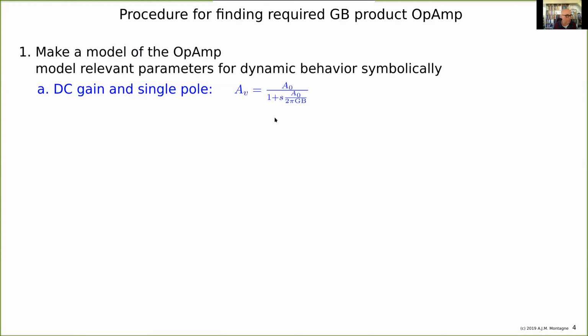Unfortunately, this is often called the open loop gain. Well, loop gain is not a property of an operational amplifier, because it's the controller and you can make any loop with it. So it's a little bit a nonsense word. So we call it the gain of the operational amplifier, and this is the DC gain of the operational amplifier. But in data sheets, you often find DC open loop gain. Well, if there's no loop, what is then the loop gain?